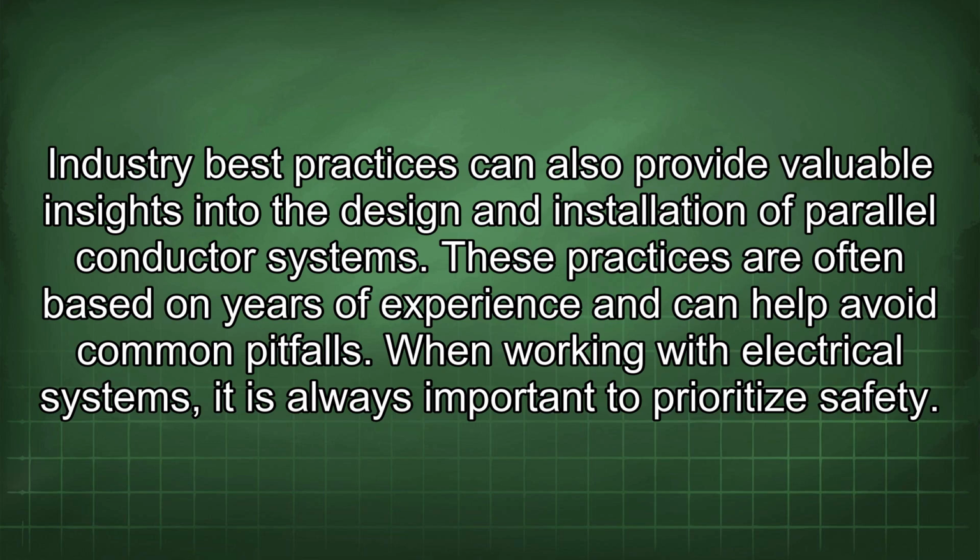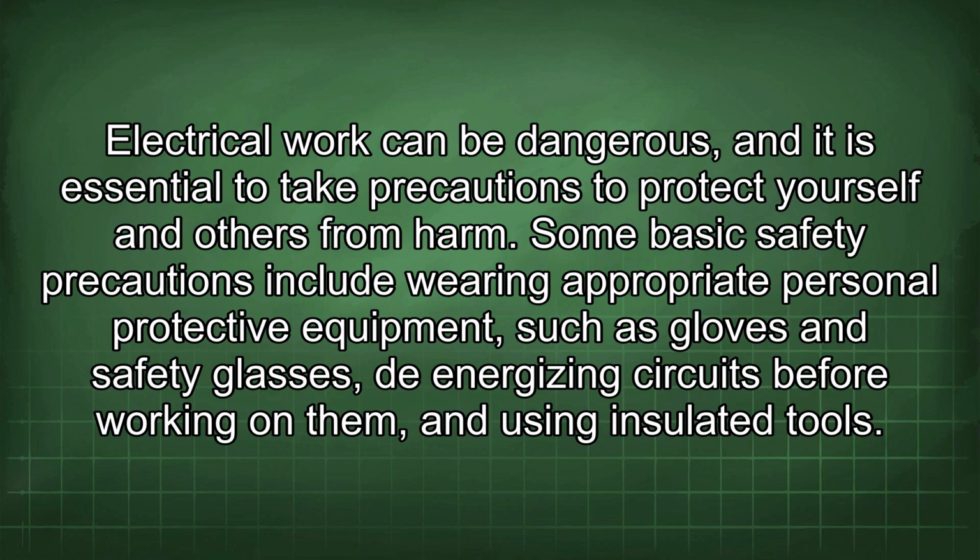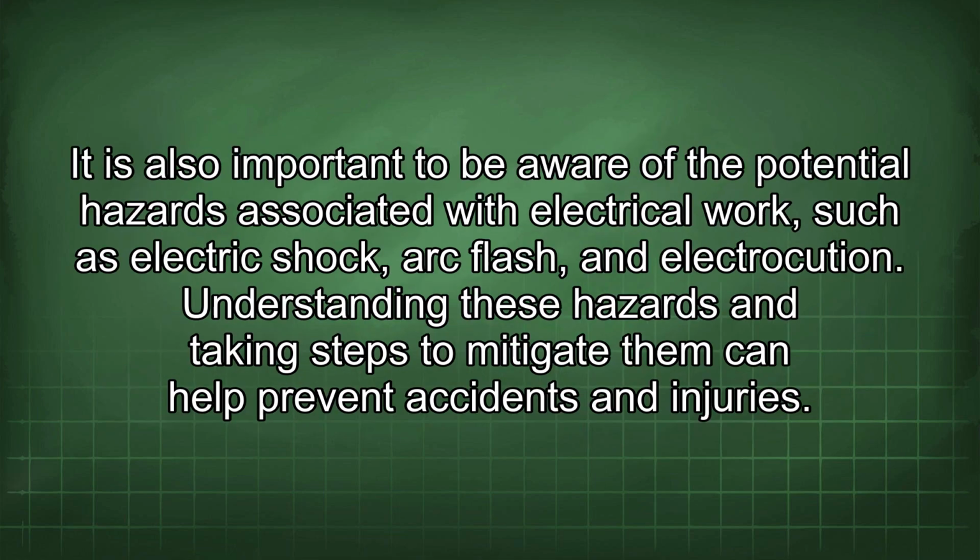When working with electrical systems, it is always important to prioritize safety. Electrical work can be dangerous, and it is essential to take precautions to protect yourself and others from harm. Some basic safety precautions include wearing appropriate personal protective equipment such as gloves and safety glasses, de-energizing circuits before working on them, and using insulated tools. It is also important to be aware of the potential hazards associated with electrical work, such as electric shock, arc flash, and electrocution. Understanding these hazards and taking steps to mitigate them can help prevent accidents and injuries.